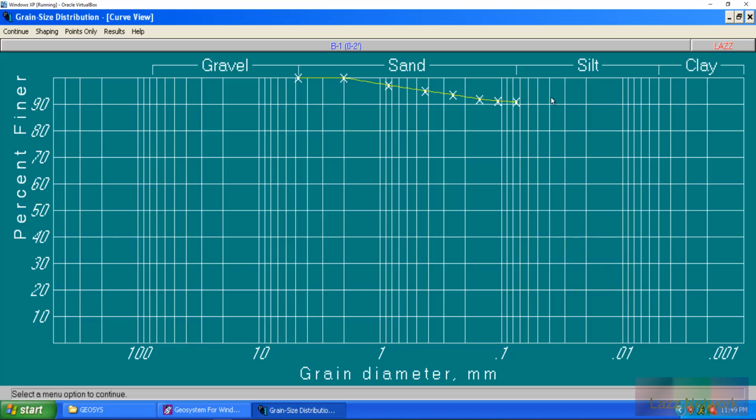If something goes wrong with your test, and I'm not saying this from experience, but if somebody really wants to investigate your work and you said you did 4.5, and they look at your equipment and you don't have a 4.5 mark or any half marks on that hydrometer, well, was it at half or was it 3/4? Was it a quarter? You can't prove that because you're eyeballing it. That's why you go to the nearest whole number.